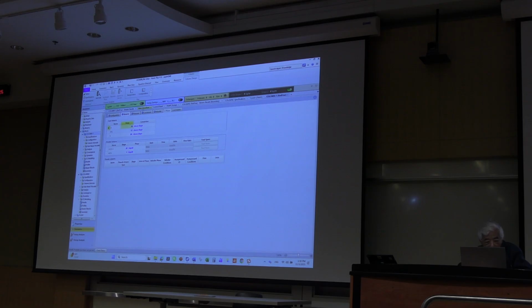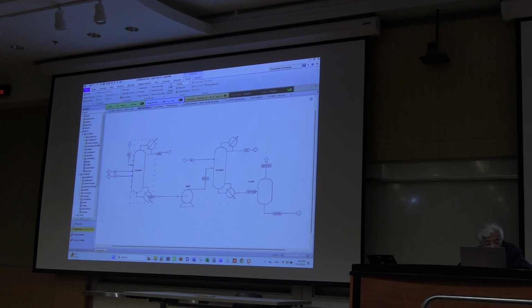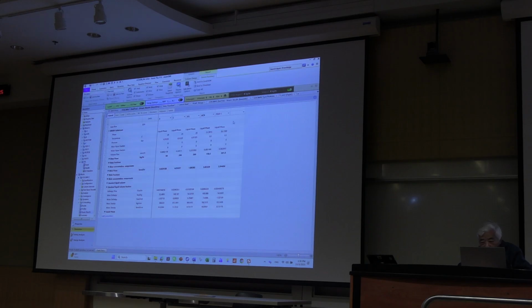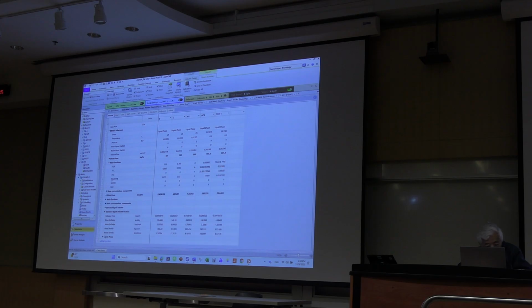How about other manipulated variables that are design inputs? You don't really need 200 kilograms per hour pure xylene. So you can lower this number as long as you get the ACN mass fraction. In this case, 0.9998. The requirement is 0.9987.